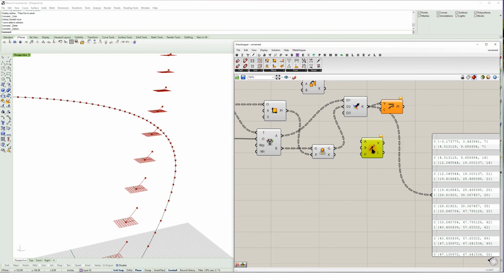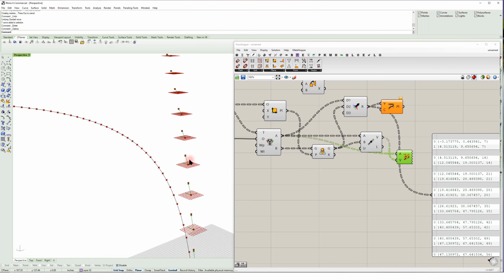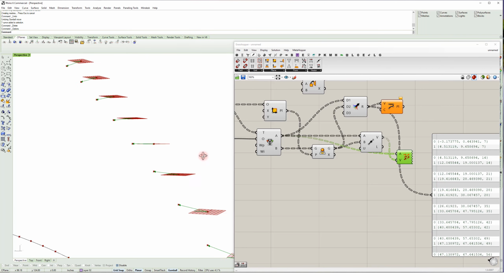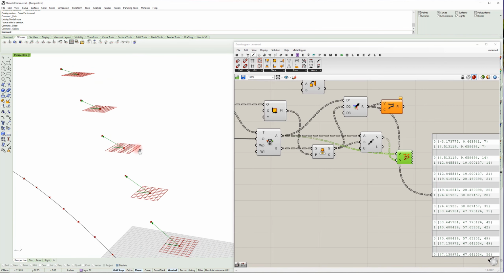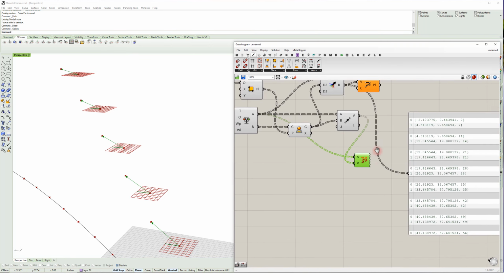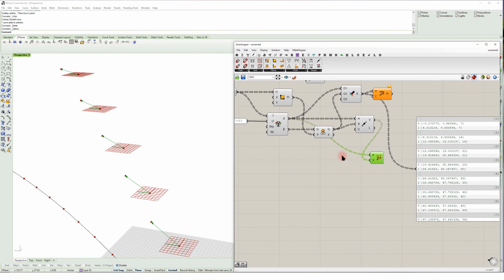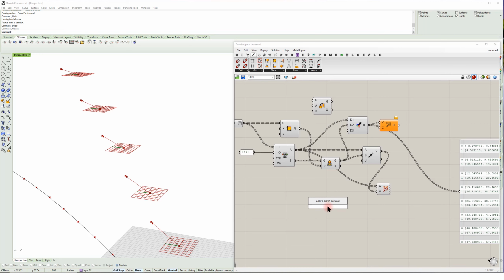And instead of creating a polyline, I just want to do A into A and the projected point into B. If I want to visualize that, I can type VD for vector display, anchor that on A, put the vector in, and you can see that's the vector we want right there. Okay, so now if we do a different way, this is better.